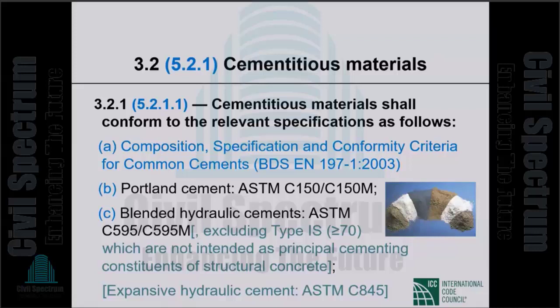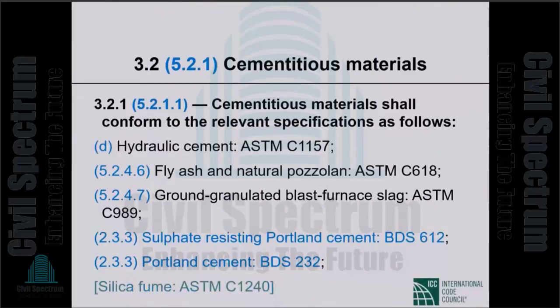Also permitted are ASTM C150 Portland cement, blended hydraulic cements (ASTM C595), and hydraulic cement ASTM C1157. I will show you briefly what those cements are.